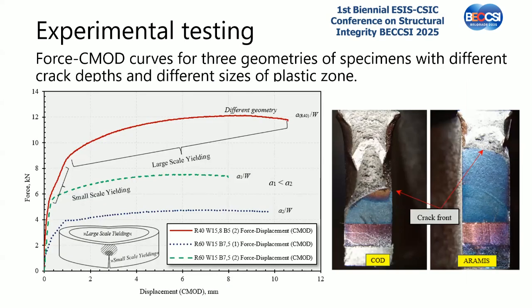institute. And you can see that when you perform the test, the specimens have a fatigue pre-crack. After the fatigue pre-crack, we marked it with heat tinting. This is the reason why we have such nice blue colors from the heat tinting of the specimen after the fatigue pre-crack. And then here is the propagation that happened during the sustained increasing of the load. So here you can see that you have three ranges. First is the linear part, and then you have a small yielding range, and then you have large scale yielding on the specimen when it achieves the maximum bending force.